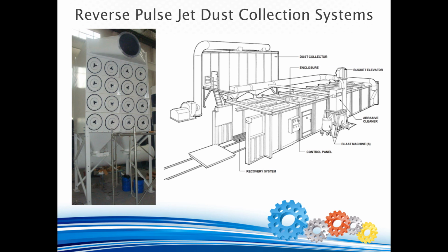As an example, let's size a 5 meter wide by 5 meter high by 10 meter long blast room that will be used with glass beads, a non-metallic abrasive. The cross-sectional area will be 5 times 5 equaling 25 square meters, or 269 square feet. Multiplying this by 45 gives us 12,109 CFM, so we can select the standard 12,000 CFM unit as the ventilation dust collector for this chamber size.